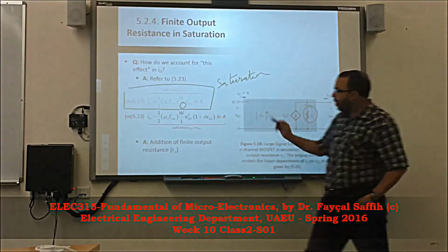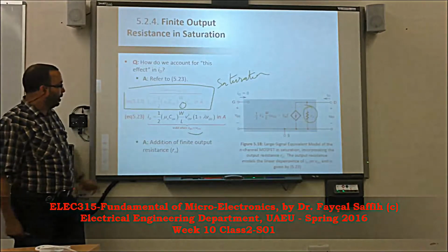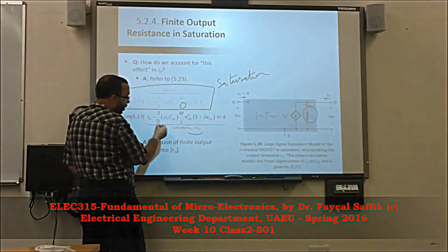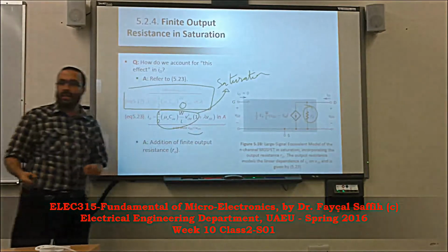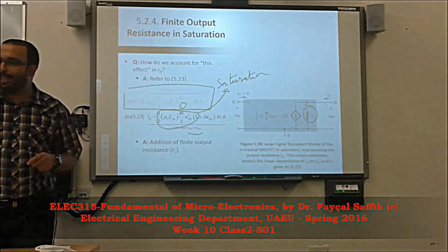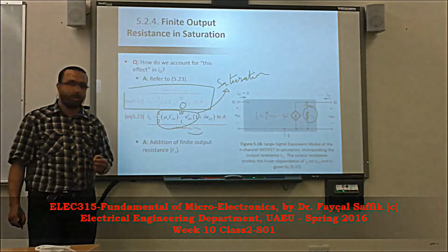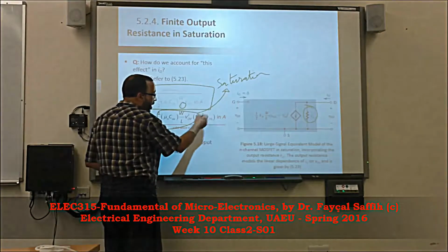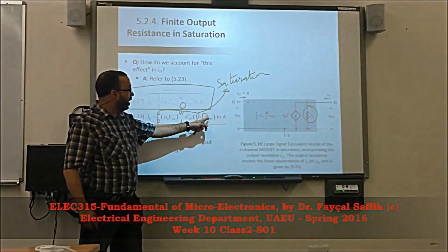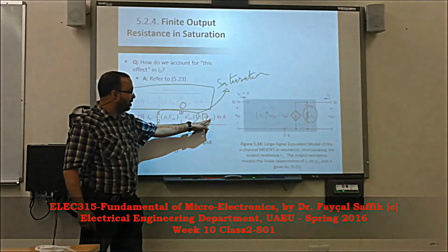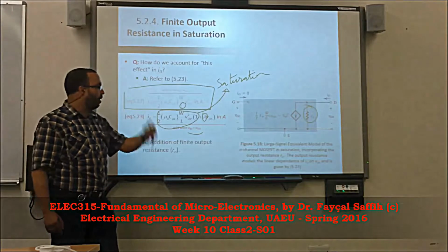So now, basically, what we have, when VDS becomes so big, is this first term, which is the first term that we have when VDS was not controlling L. And then we add just a little bit of contribution of VDS through a parameter lambda. Okay? We said lambda is the parameter that relates VDS to ID. It's just a constant. We'll see how to get lambda.